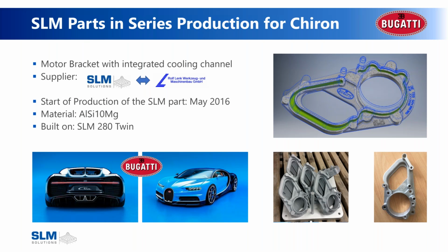Another piece that is a good example of talking about integrating parts and actually increased performance is this motor bracket, which would have a bearing inside the circular housing there. And what we see on the top right corner is that there's actual water cooling traveling through this bracket. So there's internal water cooling in this bracket that keeps that bearing cool during high performance runs and during high performance operation, which prolongs and extends the life of that bearing. And I'll get to a huge performance increase because that bearing doesn't need to be replaced. And that is on production on the vehicle right now.